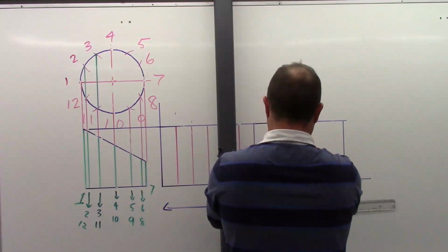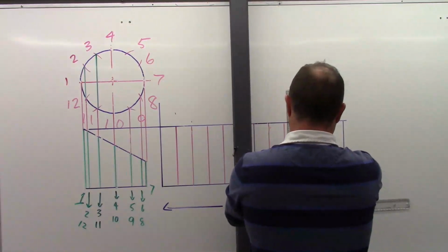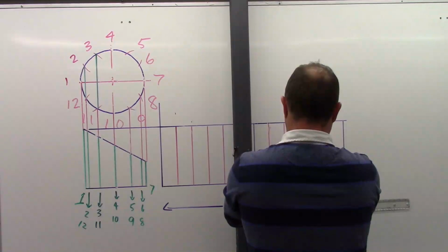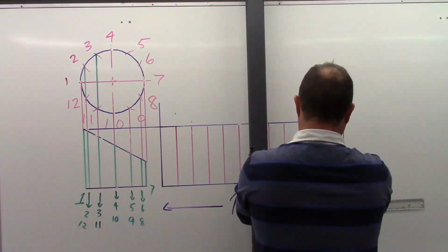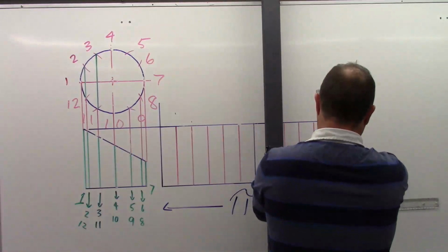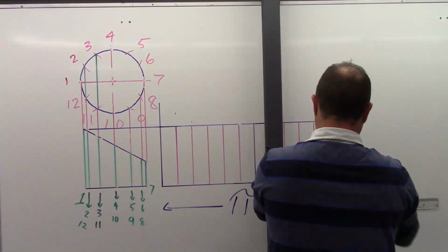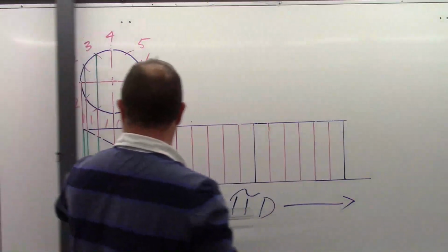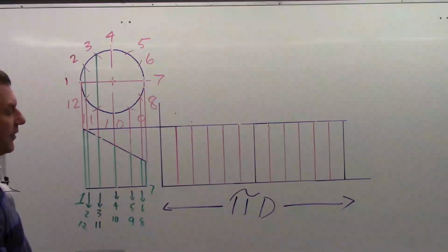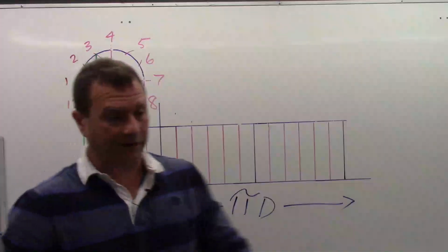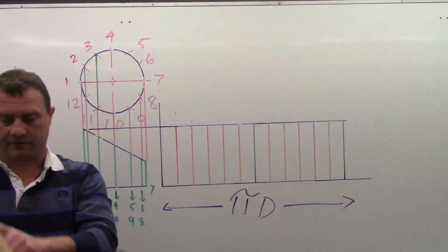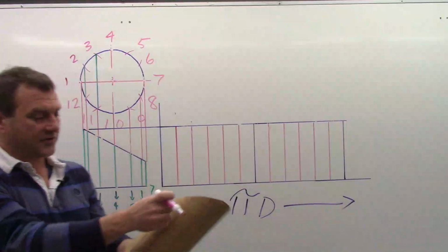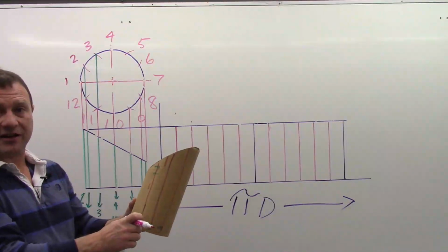Now our key component for using parallel line pattern development is right in the name. We must have parallel lines. So all of these element lines that I'm drawing in need to be parallel to one another. In something like a round piece of pipe, all the element lines are around the outside of the part, and they represent an edge, or a bend.